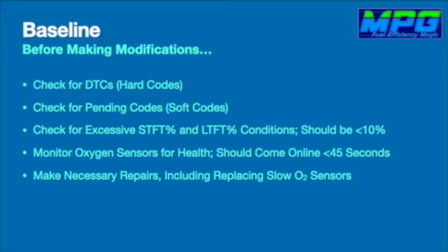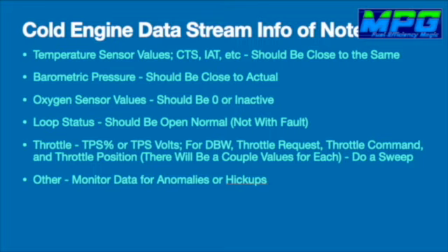So we're going to check for diagnostic trouble codes, pending codes, and readiness monitors before we do much of anything else. And then with the engine kind of cold, we're going to plug in, turn the key on, but not start, just turn the key on. Then we're going to go into the data stream. We're going to look at oxygen sensor values first.